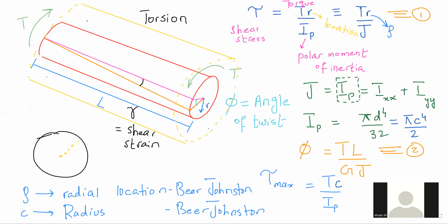100%. The polar moment of inertia of the object, because when you are twisting the object, the whole object as one entity wants to resist. So that's why the polar moment of inertia of the whole object comes into the picture. So you find, for example, in an exam, if I ask you to give me the shear stresses in one solid shaft at 3 locations, the polar moment of inertia you will find only one time, depending on whatever total radius it has. It will be those other rho values that you will keep on changing.